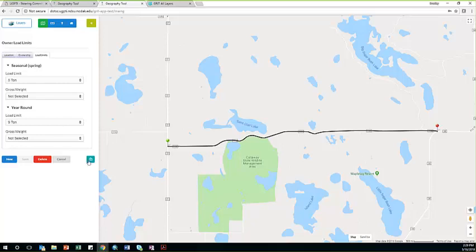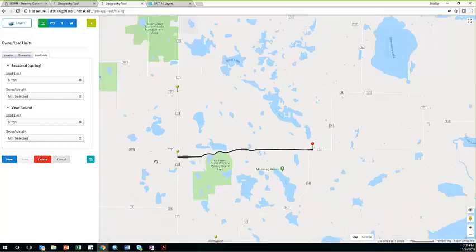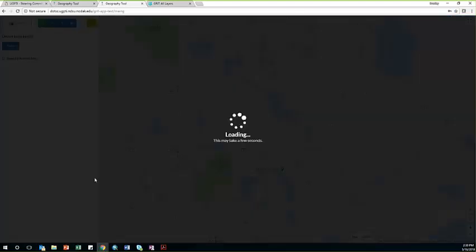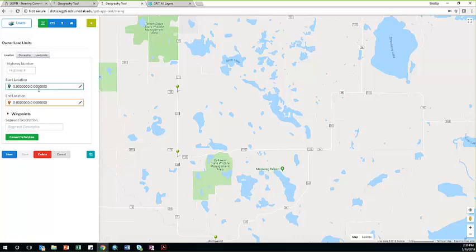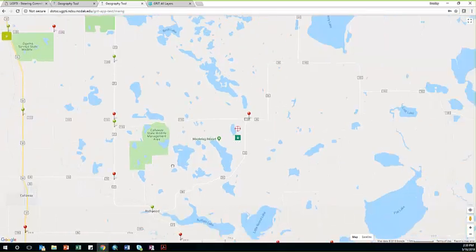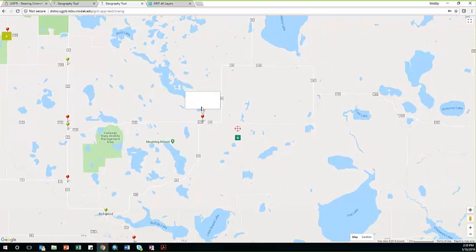I guess there's a button here that I didn't mention in the last one down below here, and that's the copy attributes. So this used to have a couple options to copy. We just narrowed it down to just the one where we can copy the attributes within one layer to another section of road. So if I'm on this one, I can click the copy attributes button and then put in where I want those to be in a new section of road. If I wanted them to go over here, I could just snap to that one